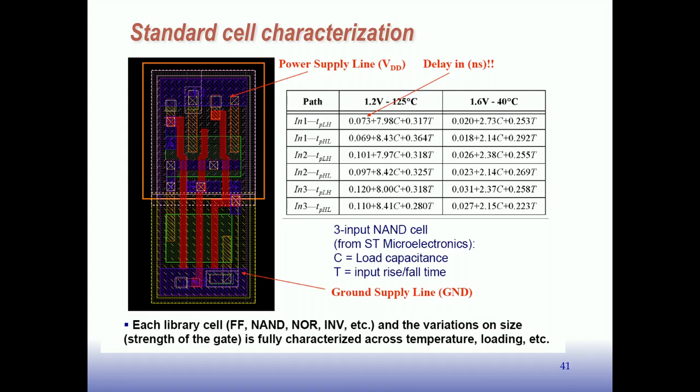Right? We're going to ignore that mainly in our analysis. But the thing to remember here is that there's some fixed delay, which is independent of the output capacitance, and then there's some delay that's a function of the output capacitance. Right? So that's the way the cells are modeled in the tools. And so the synthesis tool, when it's trying to figure out how to rearrange your circuit in order to meet timing, knows what the delay through the logic gates that it's going to map your circuit to is, so then it can make an estimate of what the critical path would be. Same thing, the simulators can use this to simulate your circuit and have a fairly accurate timing. Now, it knows what a logic gate might be connected to, say 10 other logic gates, so it can compute what the fan-out capacitance would be.